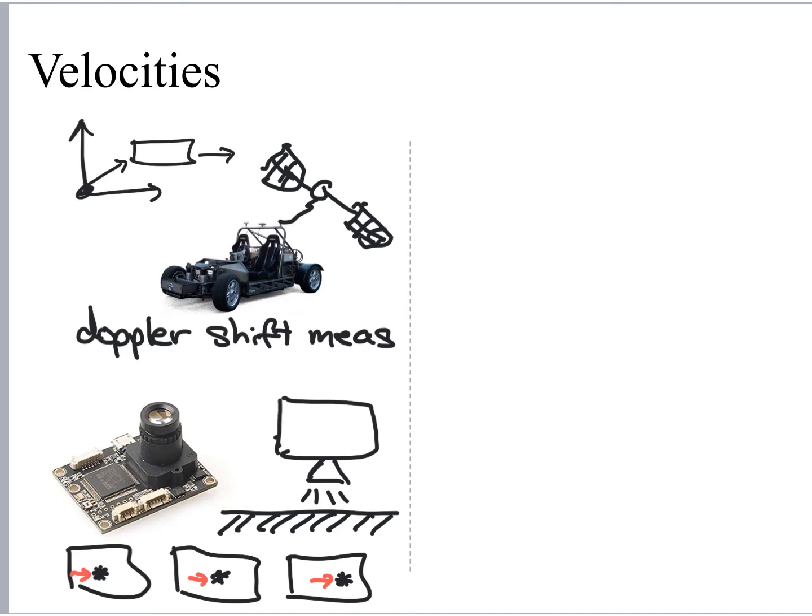The technology works relatively well, except that the camera is subject to any sort of occlusions. So for example, if you put this on the bottom of a car, you're going to get mud and dirt on the camera, and as the camera gets dirtier and dirtier, your velocity measurement is going to get worse and worse. It also tends to be relatively expensive, as does the high quality GPS that you need to do this for high precision GPS applications.